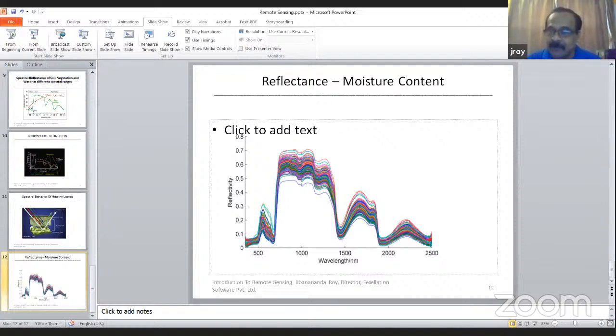And on the images, we automatically locate those points. We know we are going over Hyderabad, so this particular point is there. So we automatically find out and do some automatic registration, a crude registration. It is given to the user, and if you need a better one, you do it yourself with the aid of a map.